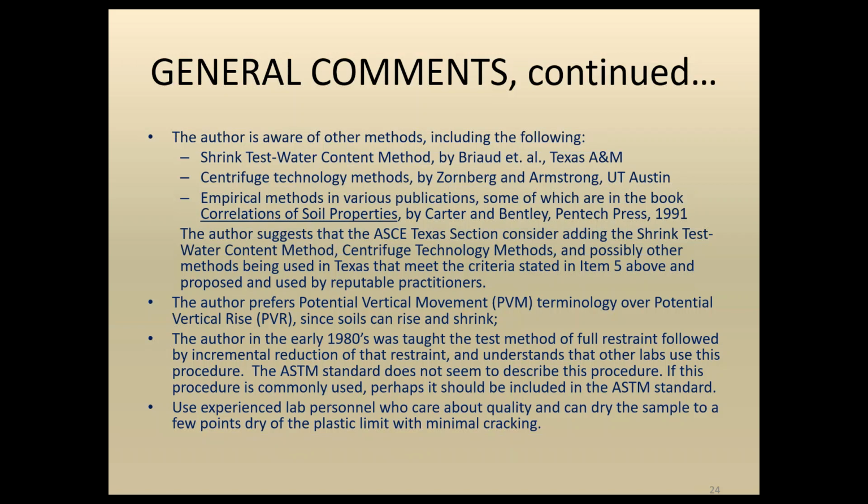And a comment that when I first began in engineering practice in the early 1980s, the pressure swell test method that I was taught was pretty much as we presented, where we have full restraint initially, an inundation followed by incremental reduction of that restraint. And I understand that other labs use this procedure and have used it for a long time.